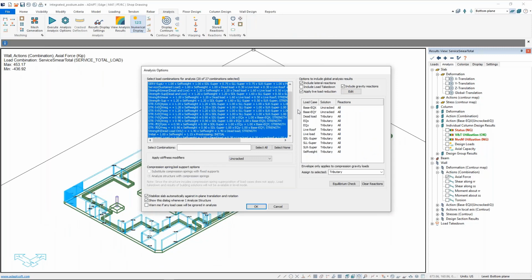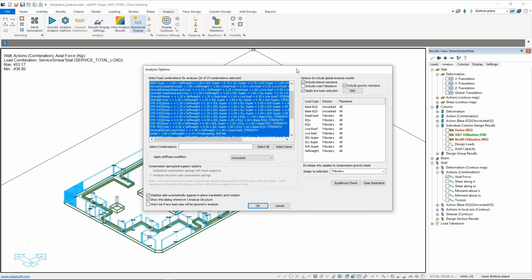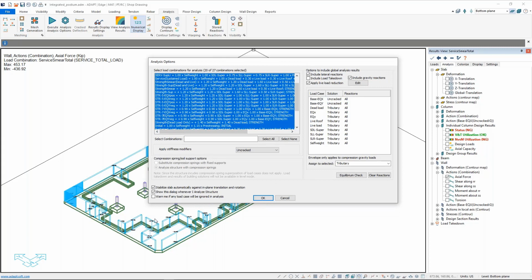So to answer, not the magnitude, but at least the question of procedurally how, when you're applying your loads to the mat, to the lowest level, you would go ahead and apply them. You can then classify that load case as reducible, trigger the live load reduction, and then come in and use it.